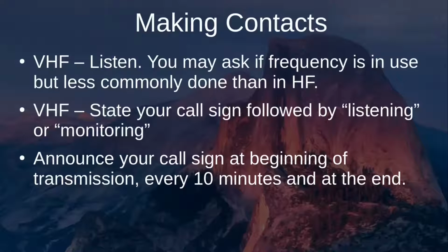This is not as commonly done as it is on HF, but it is something courteous to do, especially if you're calling on a simplex frequency or the calling frequencies on VHF or HF. So for VHF, simply state your call sign followed by either the term listening or monitoring. On VHF FM modes, you typically do not call CQ, so you would not get on a repeater and say, CQ, CQ, CQ, this is November 9, Whiskey India Bravo calling CQ. That's generally not done on a repeater.